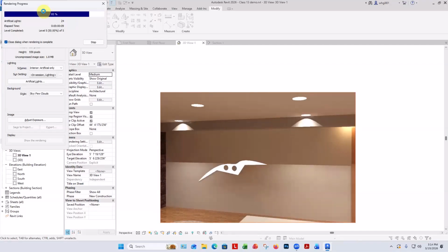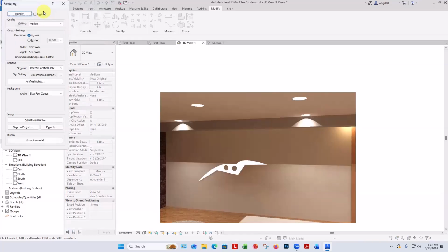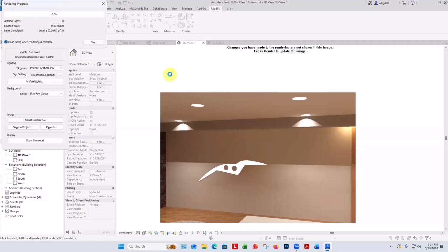Oh, okay. And this is crucially important. Here I'm on my typical medium render quality, which Revit understands as a way to save time when you're rendering. So it just uses a point light source. You always have to set these linear light fixtures to at least high to get the whole light. Otherwise, only the one endpoint gets rendered. And that's noted in here.